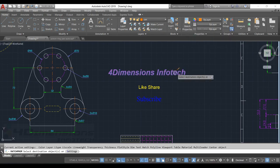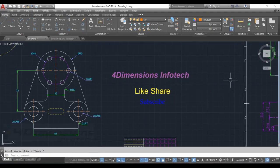Select the first text size. That symbol appears for matching. Select the other text and the font sizes are matched here. We'll repeat it again. Say match properties. Select the first text. Click on the other text. The sizes will be matched. You can see here, layers and font style will not match. Only the sizes will be changed.